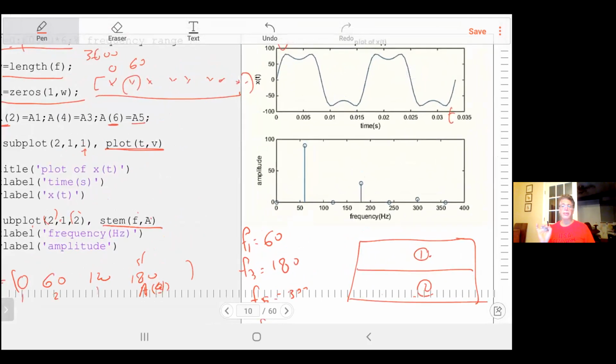Look what happened here. I added 3 components. What you got is a waveform, not pure sinusoidal. What does it prove? It proves that when you see any waveform like that, it consists of sinusoidal waves of different frequencies. It consists of a fundamental component plus harmonics. And here, the spectrum line shows you the amplitude of each harmonic component at each frequency.